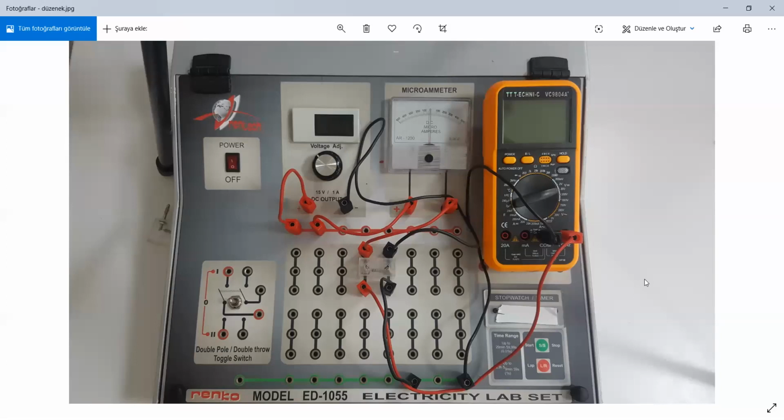To measure a resistance, we used a simple resistor and set up a DC circuit including that resistor. There was a power supply in that circuit. We used an ammeter to measure the current flowing in the circuit and a multimeter to measure the potential difference across the terminals of the resistor.